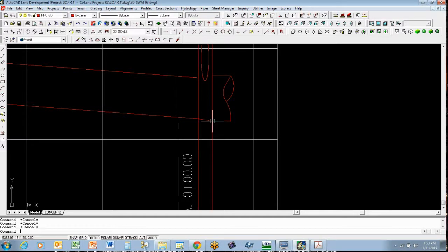Well, we probably should check in our concrete pipe design manual booklet, and we see for a 30-inch RCP that has a minimum wall thickness of 4.25. So 4.25 inches is the minimum.